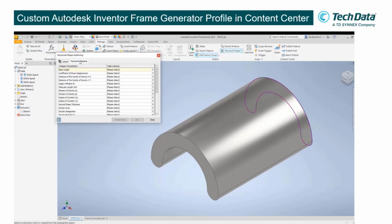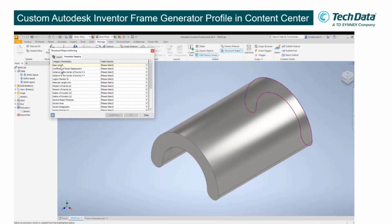All right, and then we go to parameter mapping. This is very important because we need to map which parameter the base length is reflecting. In this case, we have BL. Just now I created BL, right? B_L as the base length. Then scroll down. All this is the information that we can link back to all our parameters. In this example, I just use B_L as base length. Okay, so that looks good. So I can either click OK or publish now.